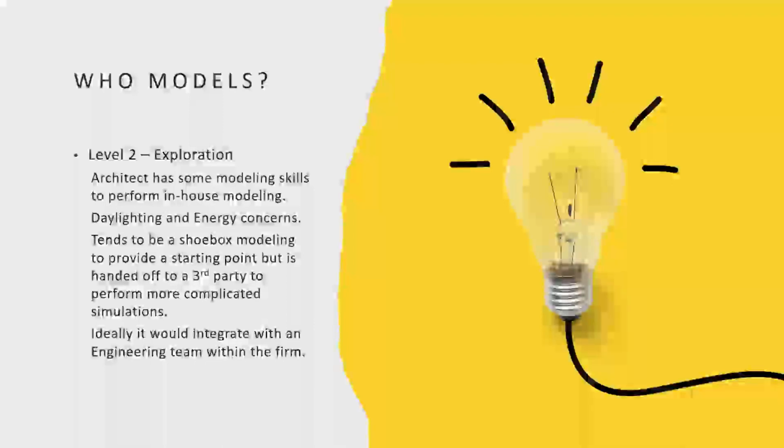If you're looking to offer it as a service full-time throughout the design process, you want level 2, exploration. You have some modeling skills in-house, so basically simple box modeling, nothing really complex. So think broad strokes. There's daylighting or energy concerns. This will let you run some basic simulations to test, hey, is there enough useful daylight for me to use daylighting as the main lighting source for my building? And what control strategies can I optimize with that? And depending on the initial results, it could be, yeah, we should explore that, or no, daylighting will be supplemental or accent at best. So it'll let you make that decision early.